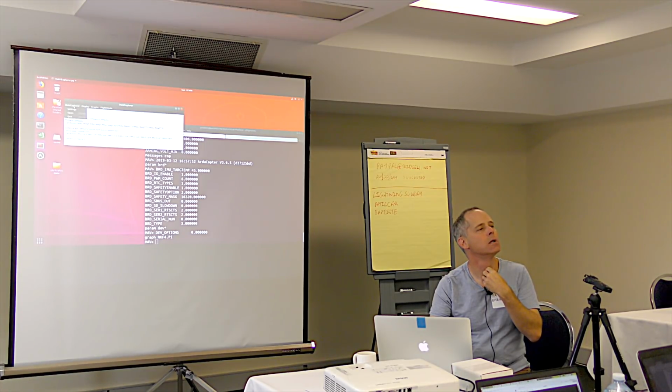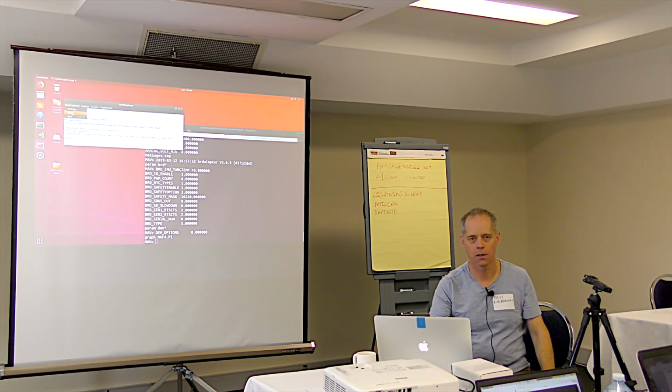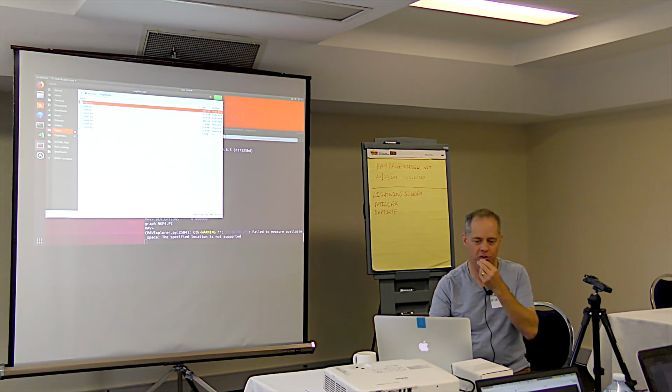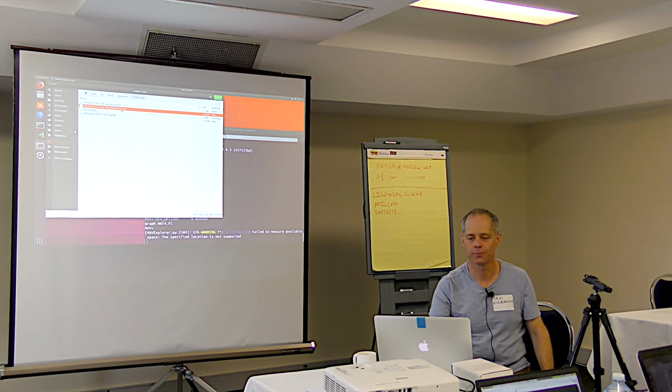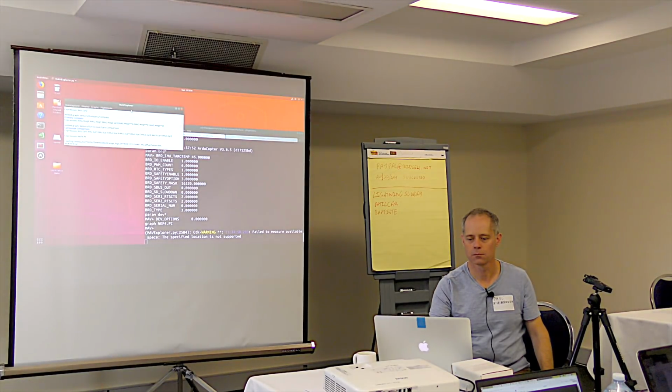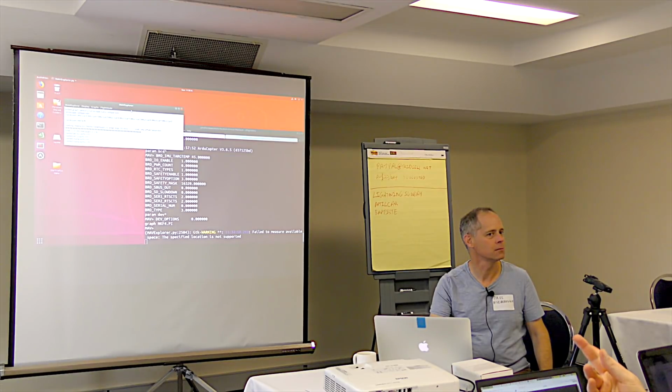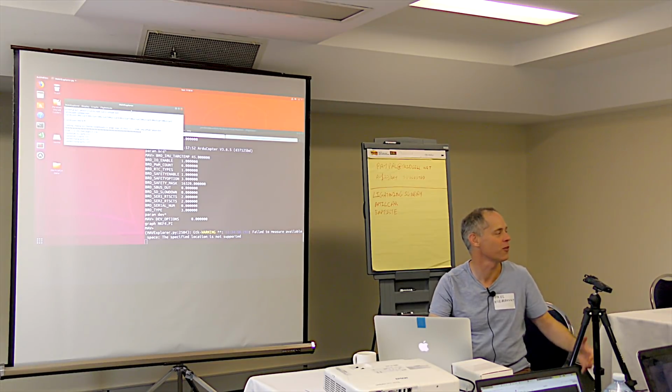Which is what I'm going on. You can certainly test the different IMUs by changing the IMU mask to only use the IMU that you want to test. Yeah, but I'm thinking about a... Yeah, I think there's certainly something that could be done better in terms of startup checks on the second lane. Do a calibration and check that all the IMUs agree. It's hard to check your IMUs though when they're all stationary. And only the gyro was off, not the accels. Yes, and it was stationary on the ground, so it was fine.